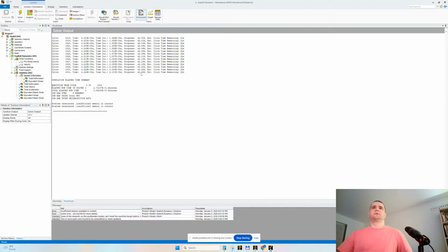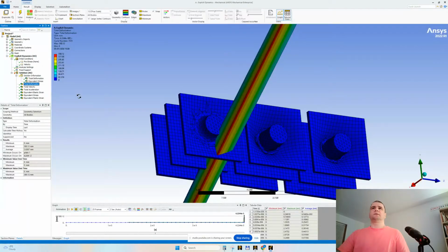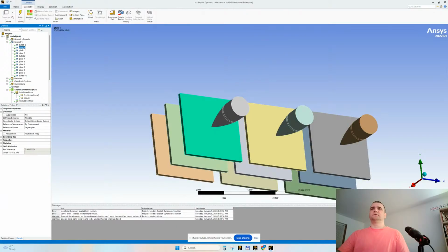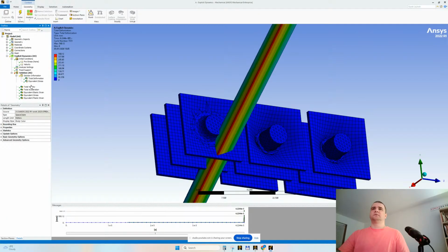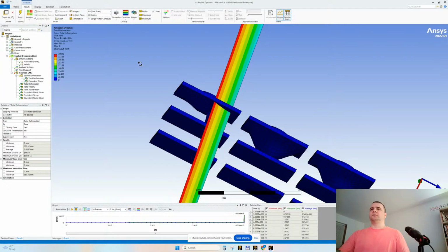Look here, it stopped at 42%. Why? Problem terminating, insufficient memory in contact. All right. Let's hit save. Where is the problem? The problem is where we predicted, where we have the linear aluminum alloy. Yes, no plasticity is defined. So this is not correct.